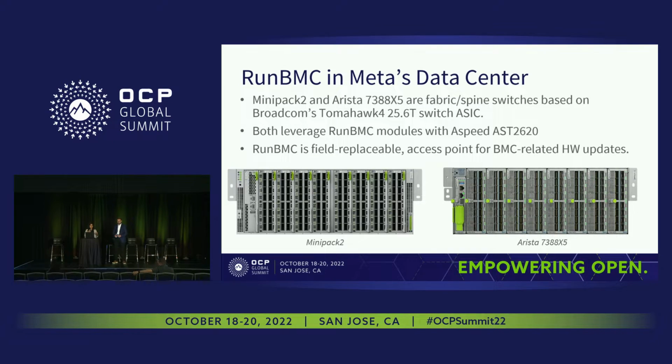The few main benefits for Meta for using RunBMC was, one, that it decoupled the BMC hardware and the rest of the system. If you look at our previous generations of network switching gear, the BMC hardware is soldered down onto larger and oftentimes much more complex PCBs, so any BMC hardware update is tied heavily to a larger PCB respin. The second benefit was modularity. We favor modularity in our system designs, and having the RunBMC module allows us to field replace or upgrade the BMC hardware if needed,